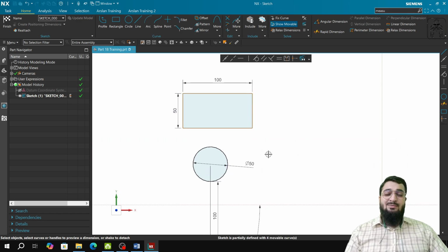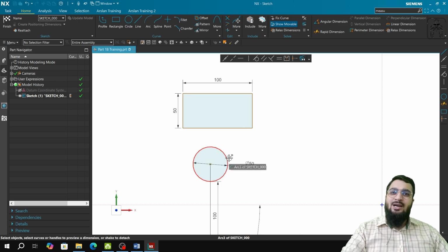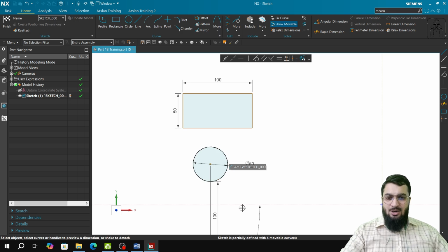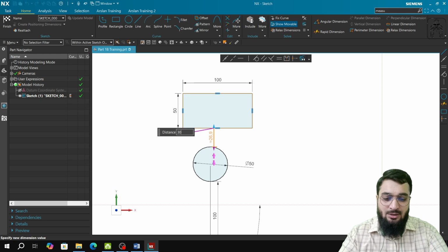So this is the use of vertical alignment, and it helps you to get a design as per your drafting or as per your sheet, and allows you to pick up dimensions using the alignment options or the geometrical constraints options. Now we have defined the length and breadth of this rectangle, but we have not defined the distance. So we'll define the distance, like it is 26.9. We'll make it 30.